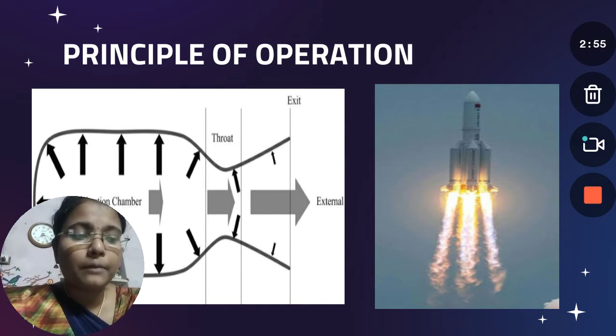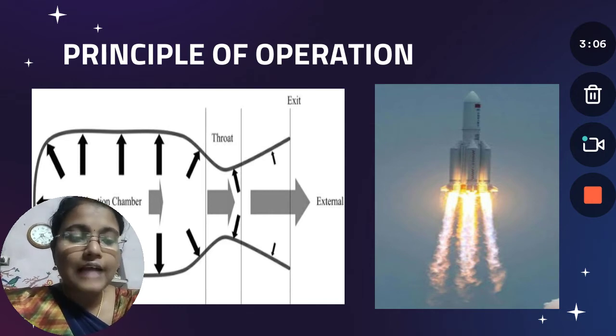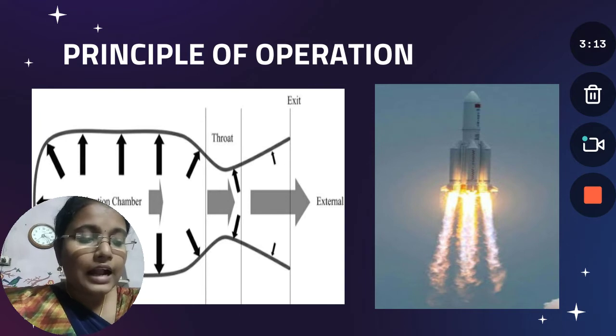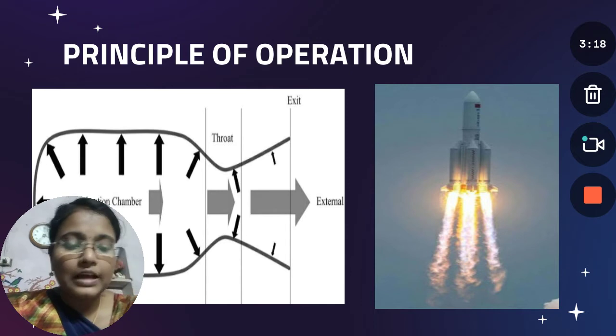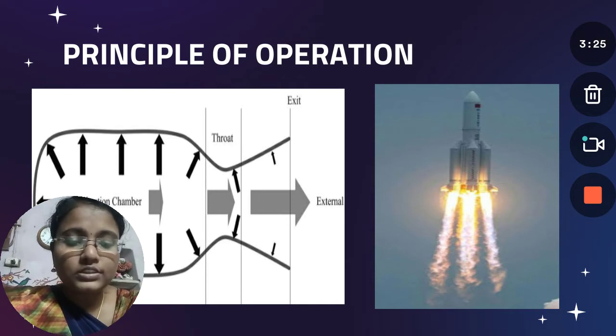The faster the net speed of the exhaust in one direction, the greater the speed the rocket in the opposite direction can become. As the propellant supply decreases, the vehicle becomes lighter and acceleration increases until the rocket eventually runs out of propellant. Consequently, much of the speed change occurs towards the end of the burn, when the vehicle is much lighter.